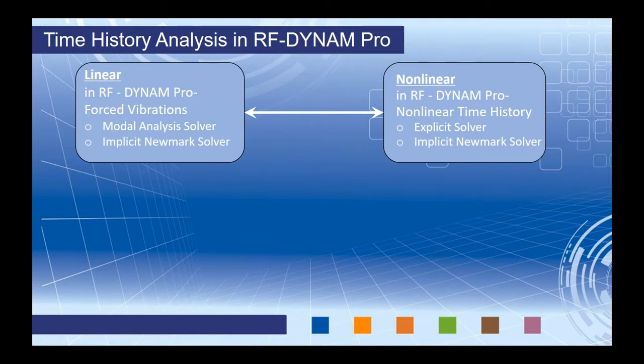Now, again, nonlinearities in the model are replaced, as I've already mentioned, with tension-only members, but also with compression-only members and cables. They're all replaced by truss members. And by the way, a truss member in RFEM is nothing more than a typical beam element that can take both tension and compression, and all we've done is release the moments. Other nonlinearities may be completely ignored, such as support conditions.